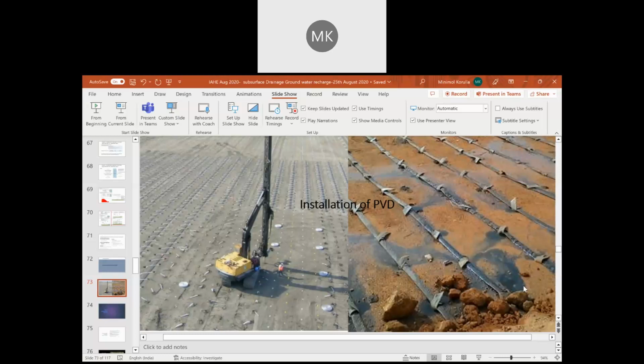The soil particles which get silted around the drainage composite are called the filter cake, and this soil cake will be increasing the efficiency of the filter. It is not going to clog if the drainage composite is selected and designed in a proper way, but it will increase the effectiveness of the filtration. Usually that question used to come, whether clogging will happen.